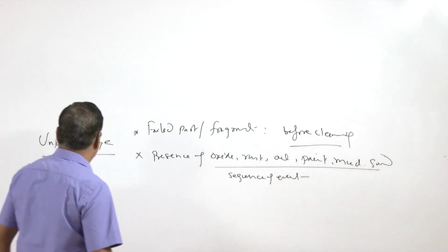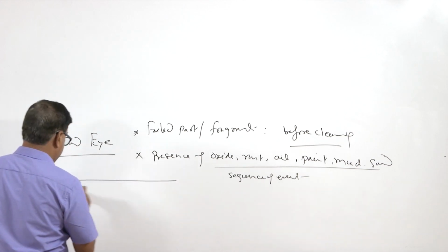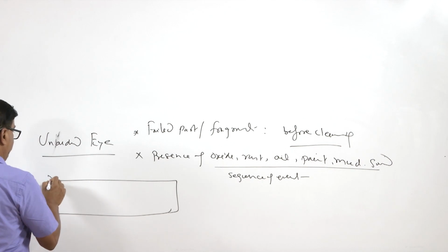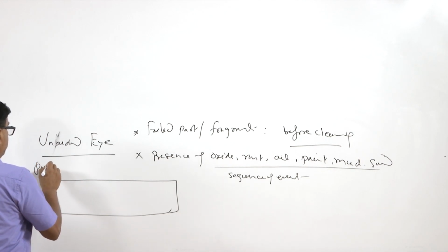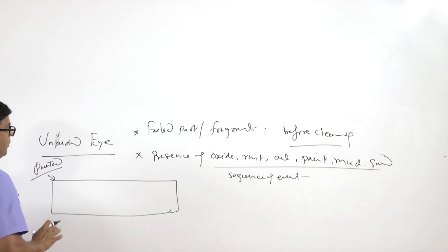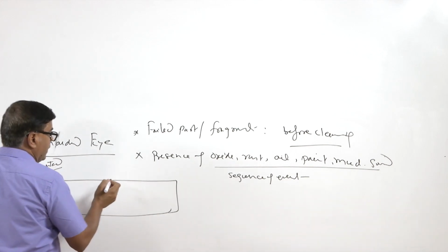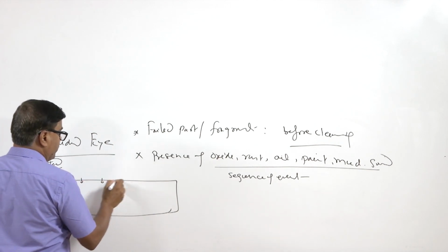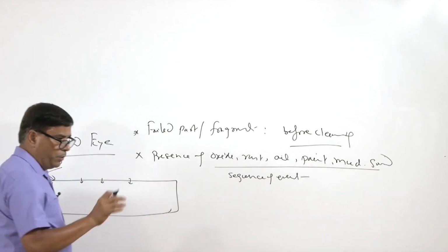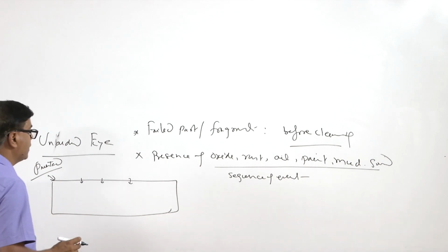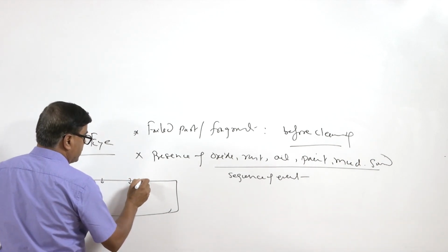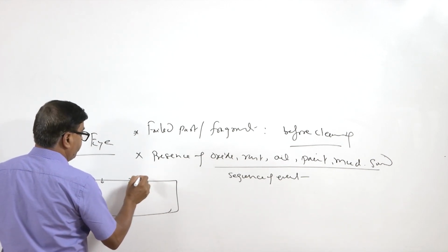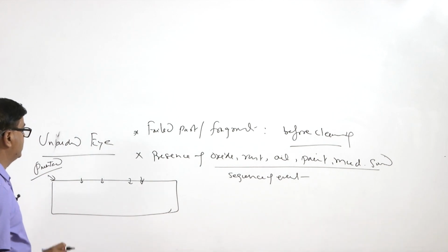For example, this was a shaft which has been used for long, and it was, say, painted about 6 months before. Whenever paint is applied, the paint will try to seep into the vacancies, pores, or cracks if they are there, and say in the shaft if this crack was present, then the paint will seep into this crack.